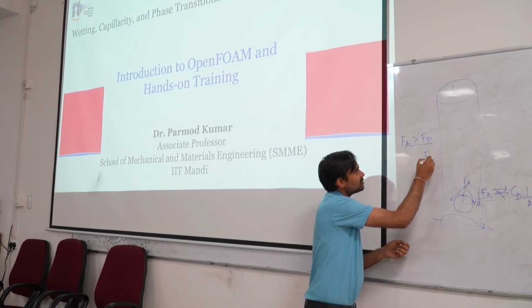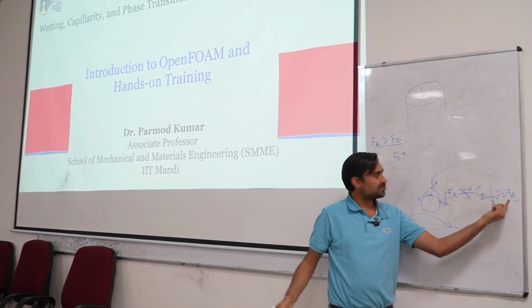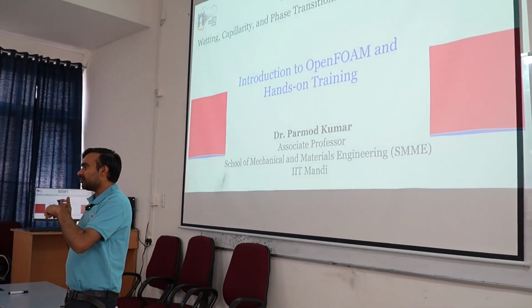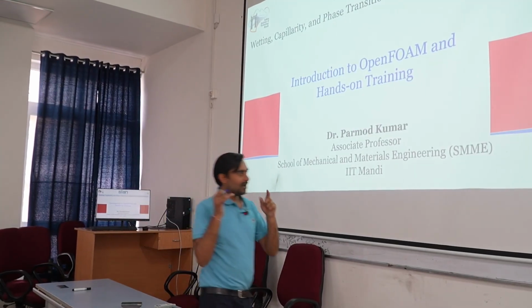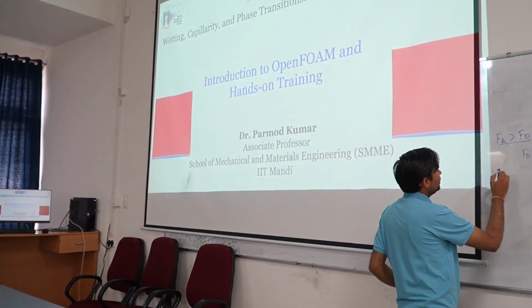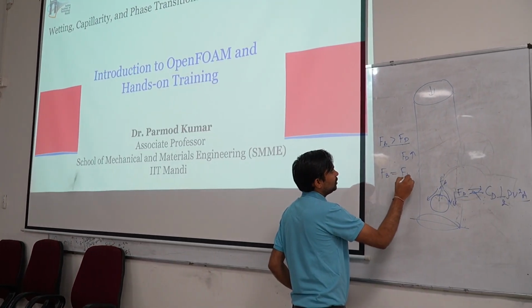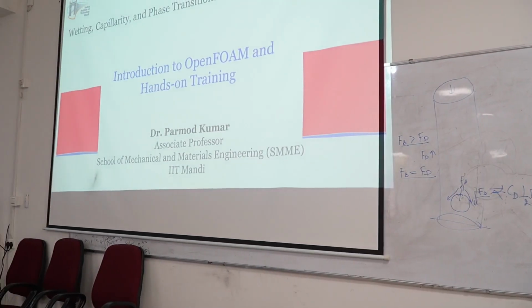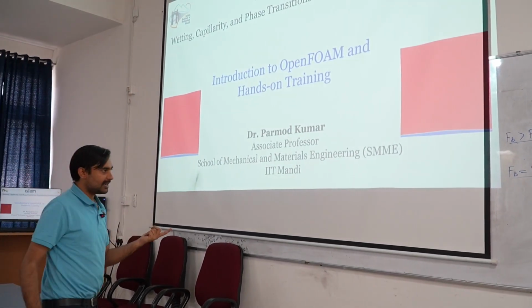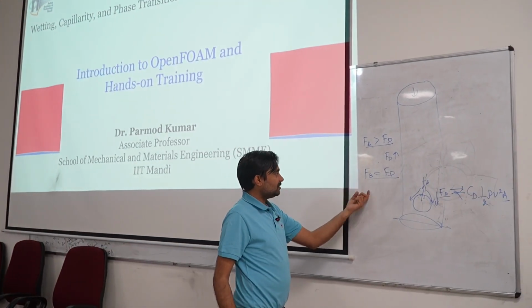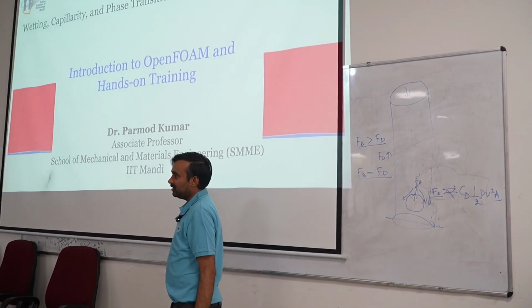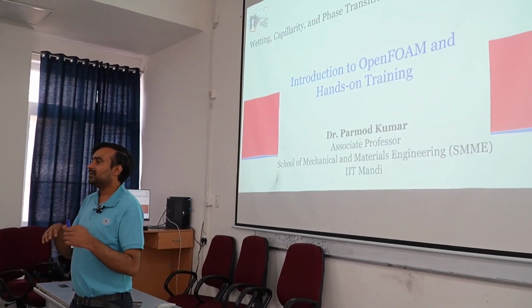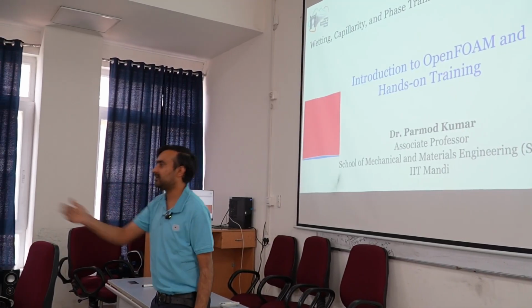The drag force is also increasing because it is proportional to the square of the velocity. So, if the magnitude of the drag force is increasing, we will find a situation where the buoyancy force becomes equal to the drag force. Once the buoyancy force has become equal to the drag force, we can say that the magnitude of the driving force and the resistance force are equal. Once these are equal, there will not be any further acceleration of the bubble.